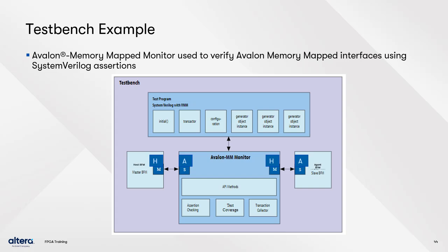The following figure shows a test bench that uses an Avalon memory mapped monitor to test components with Avalon memory mapped interfaces. The monitor's Avalon memory mapped host interface is connected to a component's Avalon memory mapped agent interface. The test program communicates with the monitor. The test program can use the monitor's assertion checking and coverage groups to ensure that all legal parameter values for the design under test Avalon memory mapped interfaces are tested.